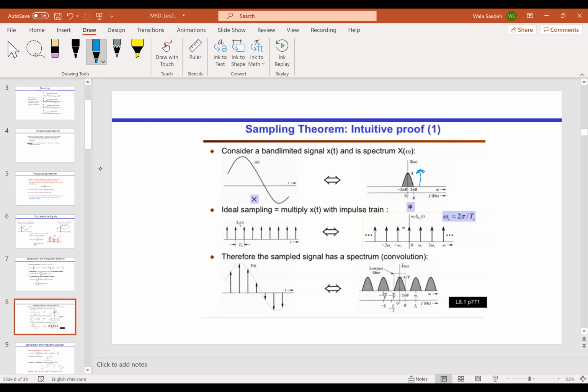This signal will again appear here. It will appear here as well. So it will appear, and it might even come nearer to my signal. So now it will also fold back here around 0. So now you can see it has come into my range of interest. And this is basically something bad. It is going to affect the quality of my signal. And that's why we need an anti-aliasing filter.